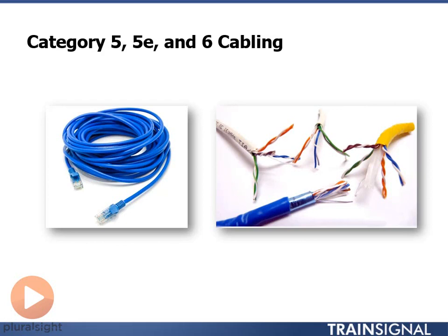So if you look carefully at this picture of the Cat 6 cable, this yellow one over here, cut open, you'll see there's this plastic strip in the middle. And that plastic strip in the middle is actually a twisted piece of plastic so that in each side there's a little corner for the wire to fit in. And it actually twists all 4 pairs at a very precise angle so that we prevent as much crosstalk as possible.